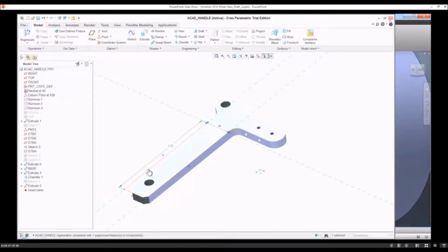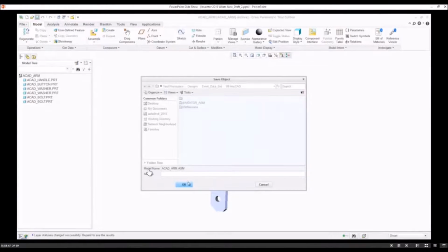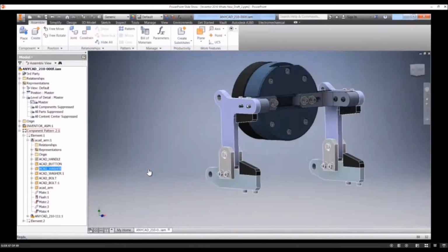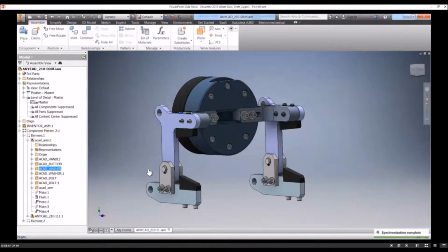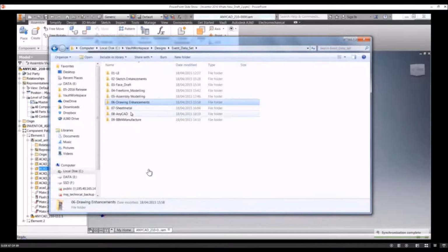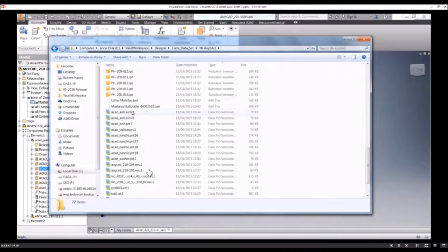When we've done that, we can then close this down, make sure we save the assembly in the other CAD system. So obviously this isn't something that you would be doing. You're the Inventor user, you're just receiving this file in, so that bit there is a little bit of what someone else might do in a different system. Now I'll come back into Inventor, but you notice there's no automatic update involved. That's because some CAD systems save with a .version number. So in order to get over this, we can simply delete that file and change this file to a different